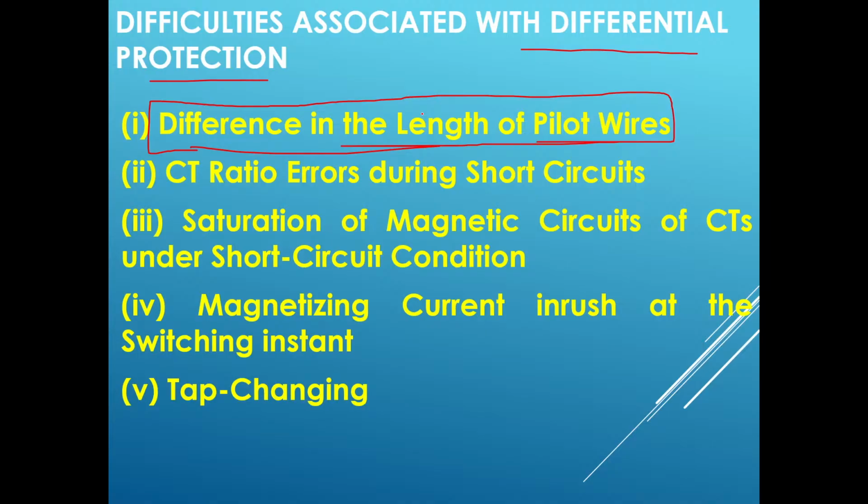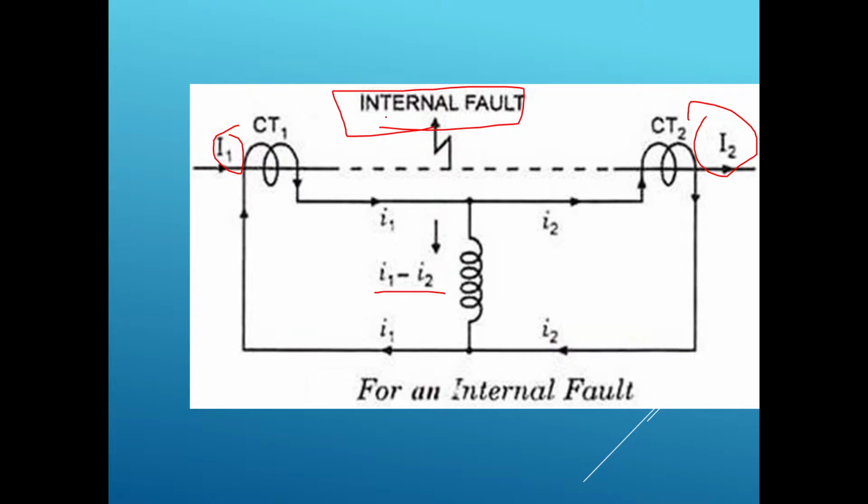Normally it is not possible to connect the relay operating coil to the equipotential point. The relay should be connected at the equipotential point. So this point you can call the equipotential point. The relay should always be connected at the equipotential point, then only an equal amount of EMF will be induced across the secondaries when the same current is flowing.